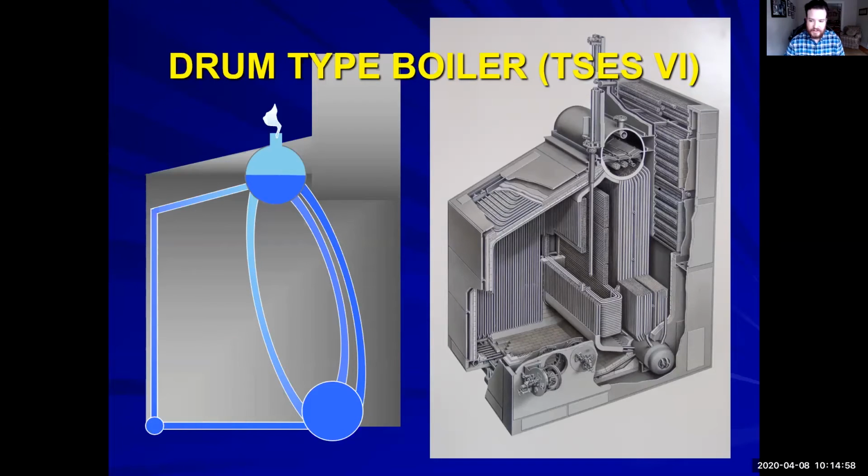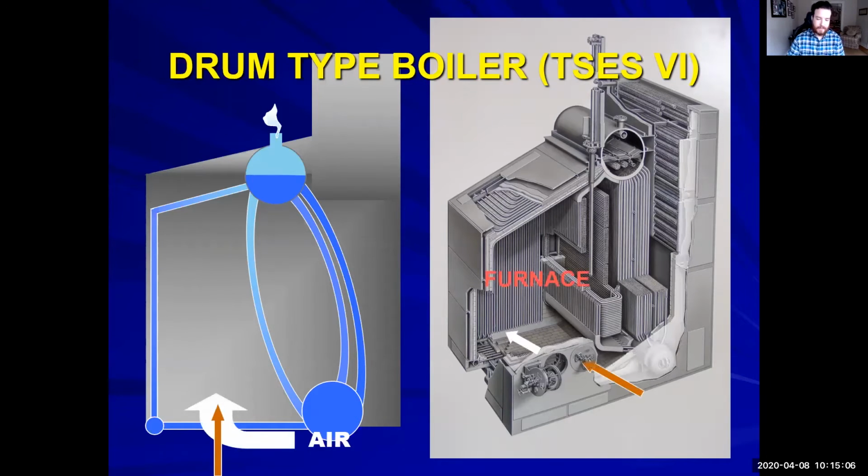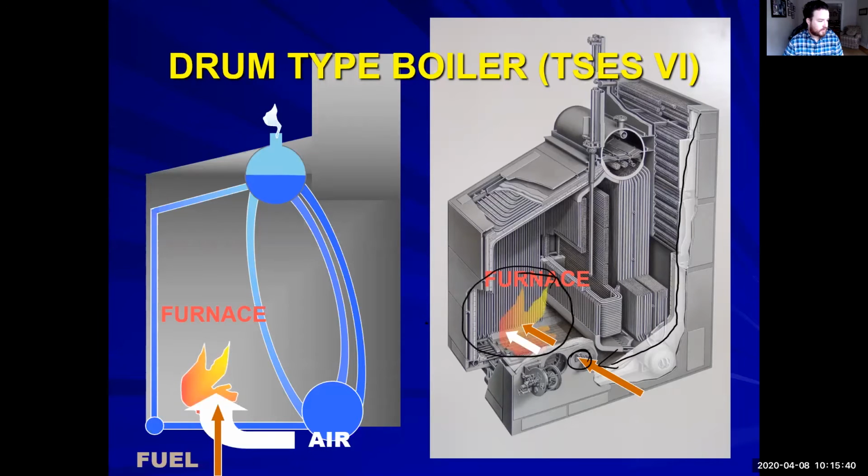During Mud Cruise, we're going to go deep into all of these, but for now, let's just label a couple. So first of all, we have our air and our fuel, because any sort of flame needs fresh air in order to burn. Our fuel goes through our burner tips. Our air is drawn from in between the boiler and the sidewall of the steel, so it's preheating the air basically. You have your flame, and this is where it's actually burning. You're not going to have flame all up in here. This is where it's basically going to stay. It's going to be a cone shooting out of your burner tip.